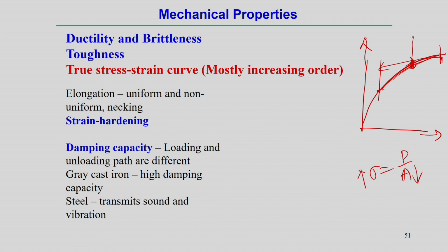That effect is called strain hardening. Different materials have different kinds of strain hardening effect. For example, a titanium alloy has a very low strain hardening effect, so not much increment with reference to the yield point value with further straining of a sample.